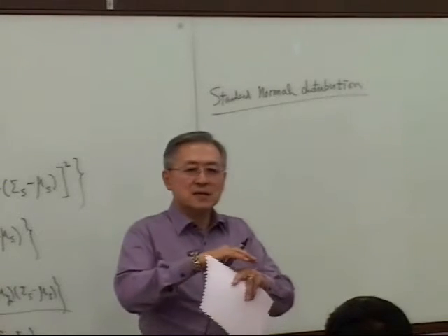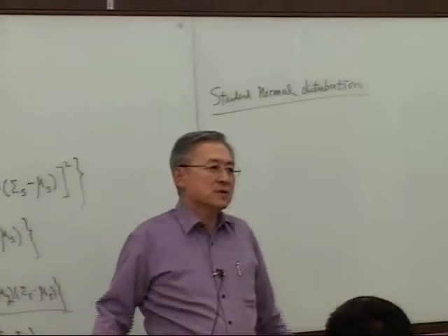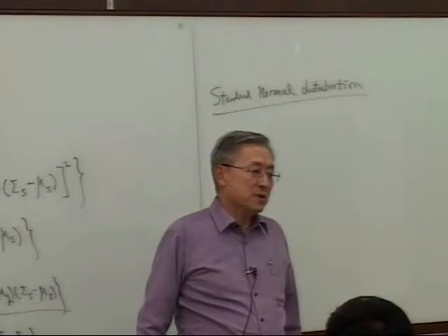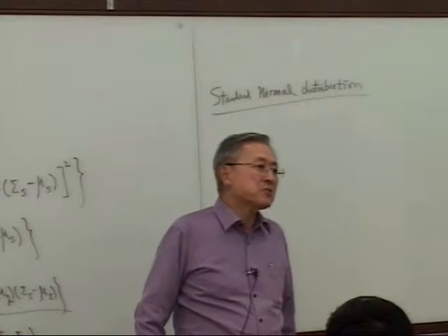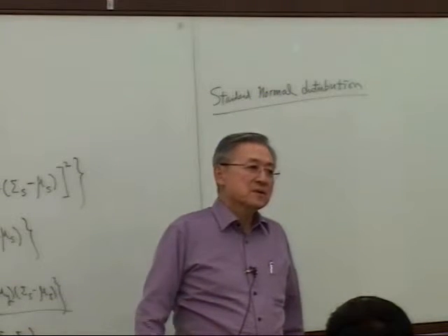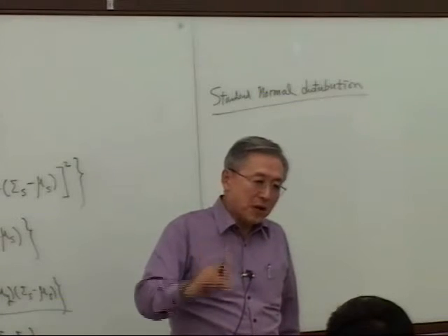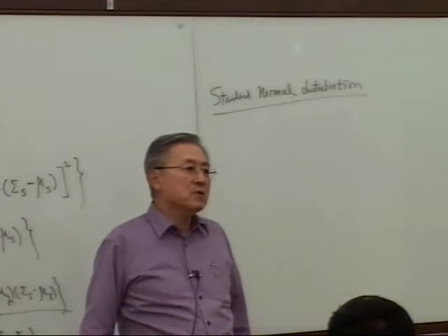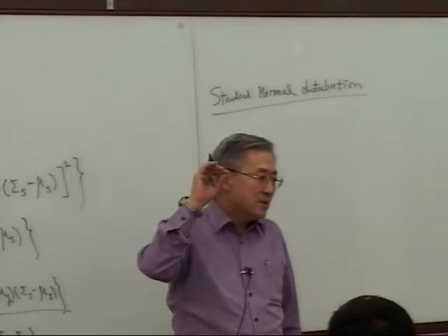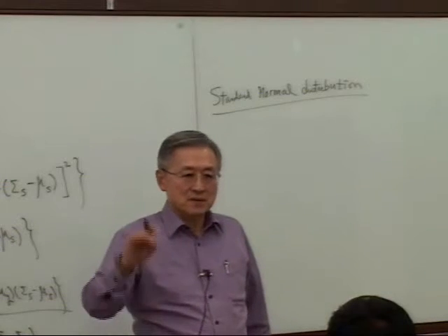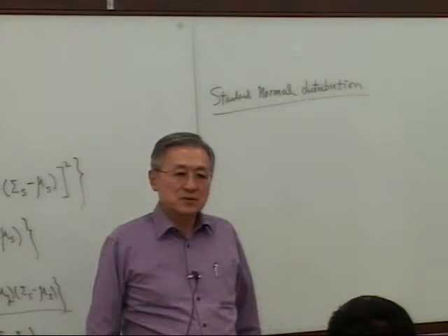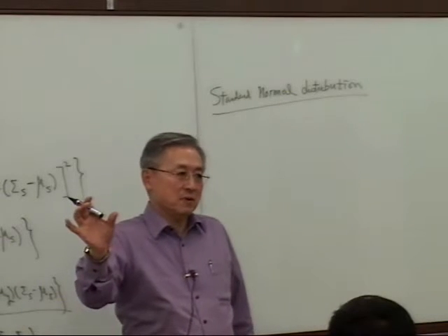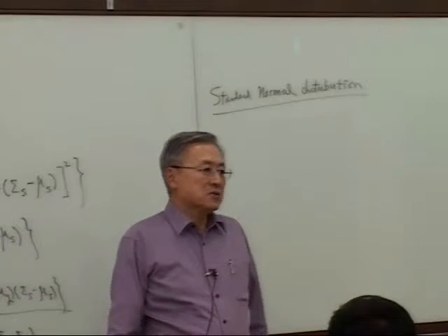Then when you throw that random variable with a formulation into the space, you can really nicely arrange all the random variables independently of each other. Then you can convert the integration of the multi-dimensional probability density function into the multiple integration of individual probability density functions, which is really nothing but the multiplication of each integral to get the structural reliability.